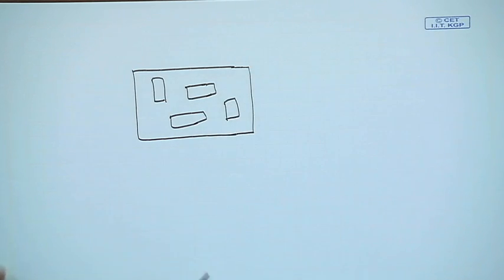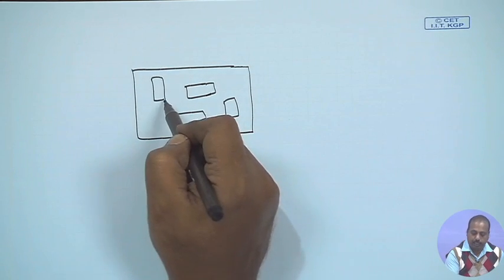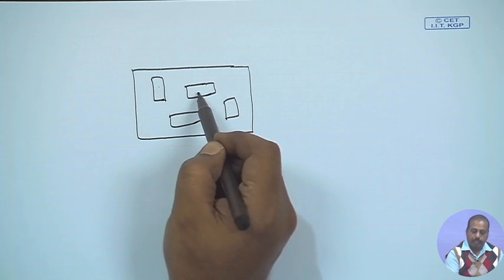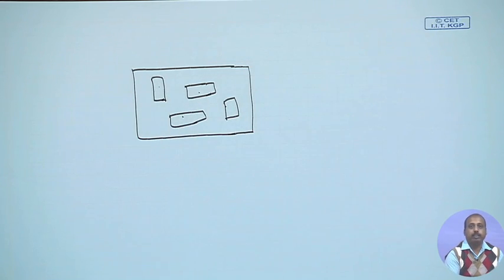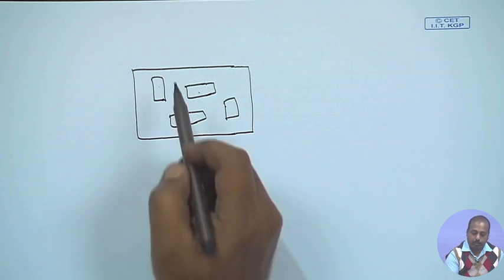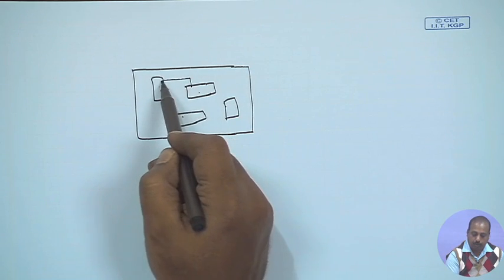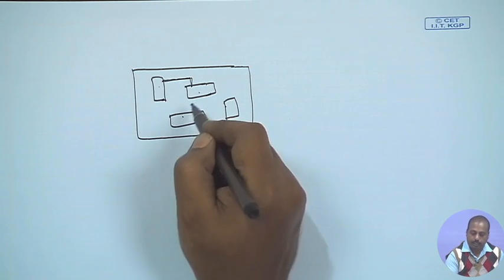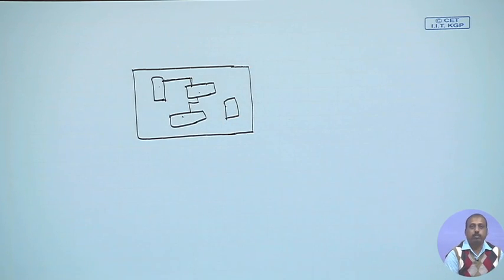These chips are shipped into the market by the vendor, and they have done their own testing. So naturally we can be confident about their correctness. These chips may be assumed to be correct, but what we need to test is the interconnect between the chips. This interconnect is a copper line running between two chips, so that line has to be tested. Similarly, this may be another copper line running between the chips, so that has to be tested. This way we need to test individual interconnects only.